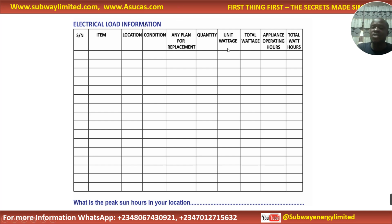Remember, we talked about electrical rating, how electrical loads are rated. So how many watts is each of them? Unit watt, that is, this LED bulb, what is the wattage? This fridge, what is the wattage? This laptop, what is the wattage? That is the unit watt. Total watt talks about when you multiply the quantity here and the unit watt here, quantity here, unit watt here, it tells you the total watts.